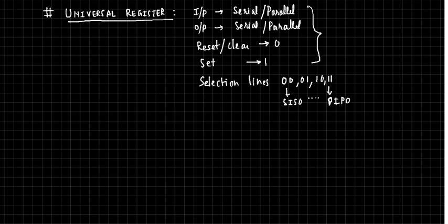Say, for example, I want to design a clock. In a clock, I am always keeping track of when the 60 count is reached. Suppose the clock period is 1 second. For 60 seconds I will count it as 1 minute, for another 60 seconds I will count it as a second minute, and so on. So I'll have to keep track of 1 happening, after that 2 happens, 3 happens, and so on. So it's like a prescribed sequence of states which happens. If the states of a register are defined like this, such a register bank is called a counter. Okay, so let's see what counters are.